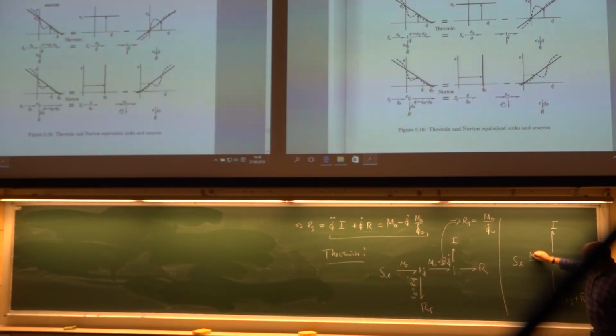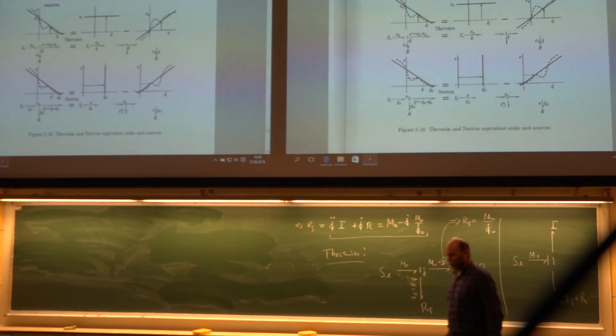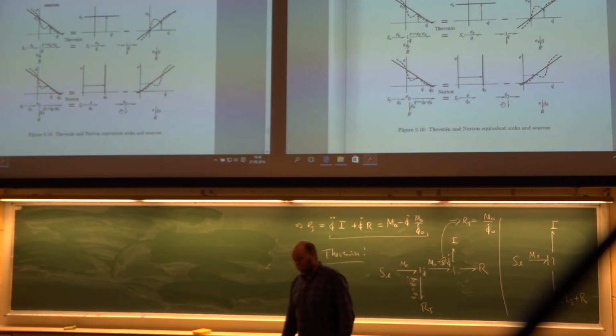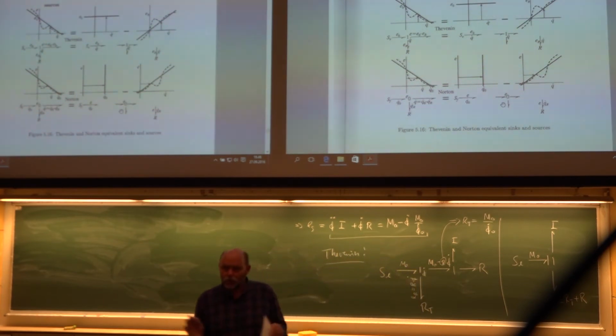So here I have now a constant source, ideal source, effort source. What about causality here? Well, you start always with the sources. So the causality has to be towards the one junction. What was the rule for one junction? You should have all strokes towards him except one.